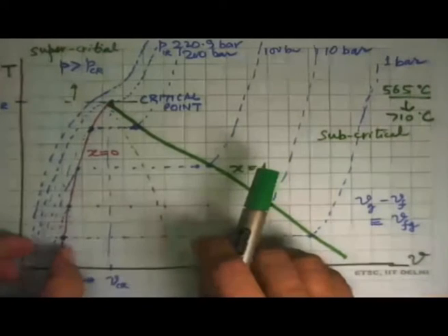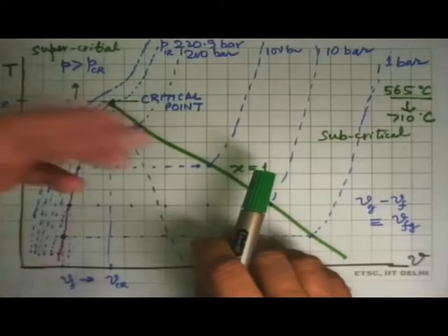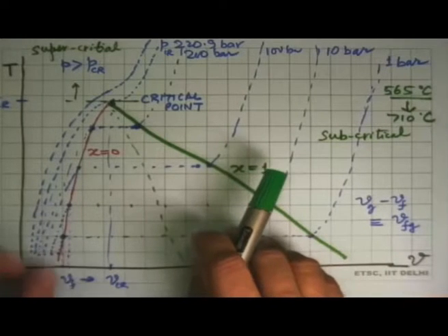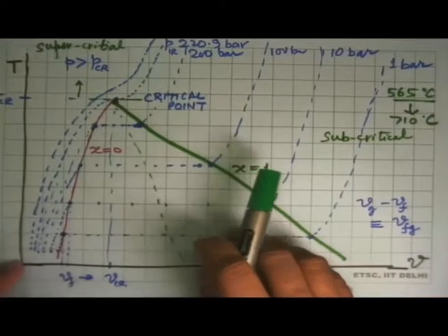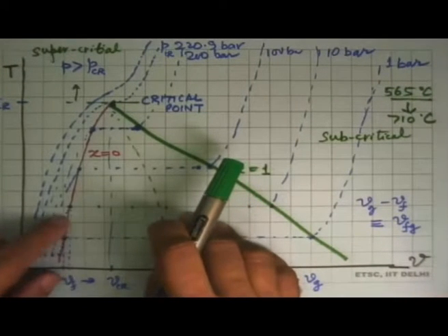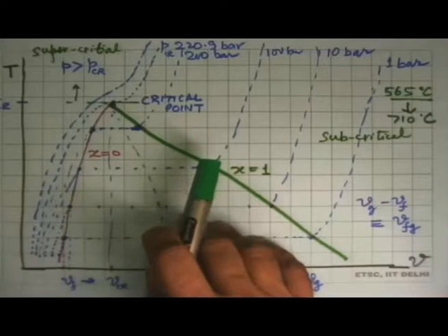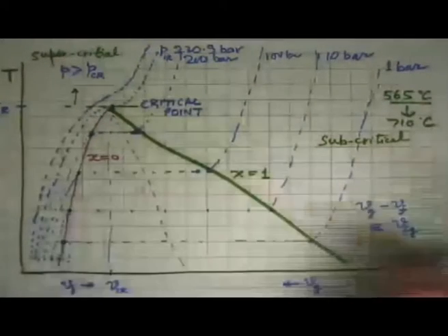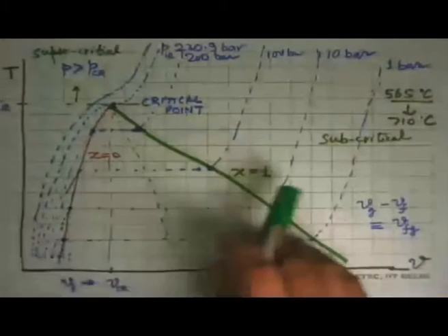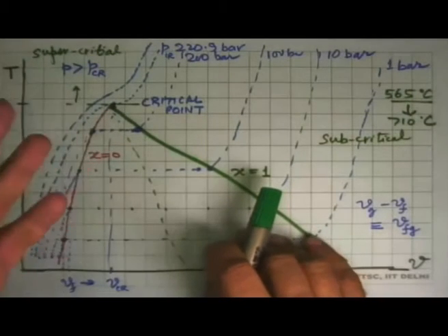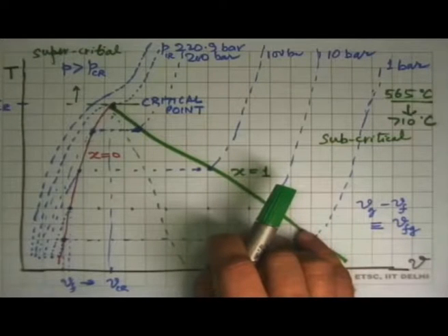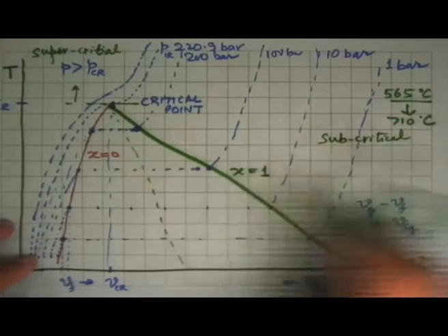So the upper limit of some sort has been set in the properties. As I'm saying, all of this is a huge exaggeration. In the notes, I've given some plots where all of this just becomes very, very small. You can see that in books also, that the effect of pressure on specific volume is very, very small. So as an approximation, one can even say that water at 40 degrees Celsius and 1 bar has the same density as saturated liquid at 40 degrees Celsius. Okay.